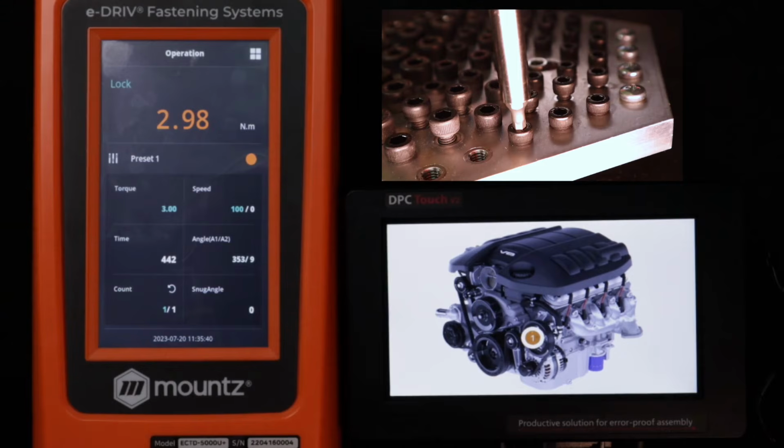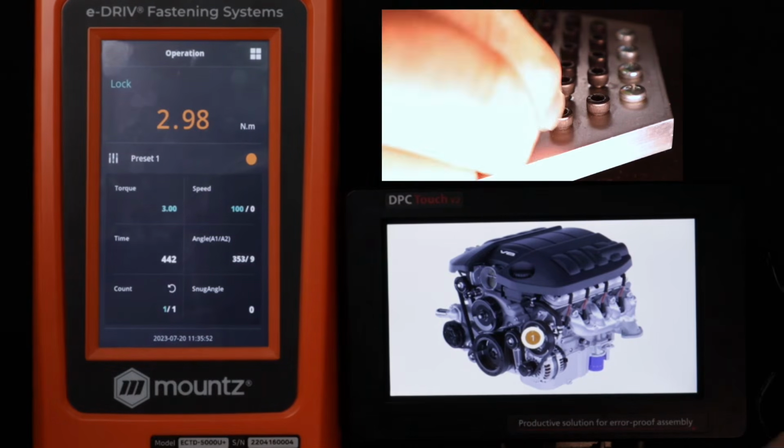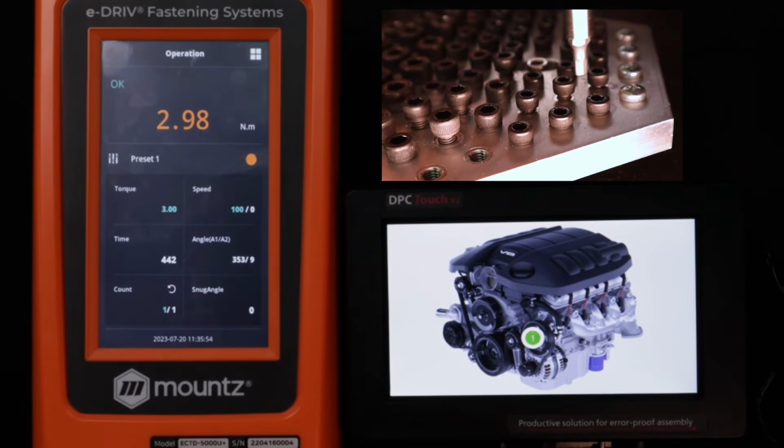But in any case, we have the ability to error-proof this assembly process, so the operator doesn't have the ability to make a mistake. They can't go ahead and use the tool in the wrong location, because the tool will only have power in the right location.